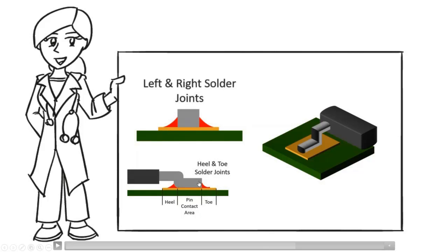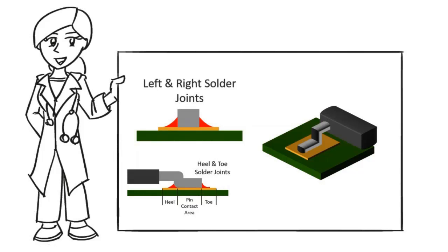So you can set up design rules that say, how much toe fillet do I want, how much heel, how much contact area there is, side fillets, in order to produce a good quality solder joint, plus being able to verify, did I put the pins all in the right place on the part? Is the pin shifted or not in any direction? You're basically modeling up the design to confirm that your solder joints are going to be acceptable in the assembly process. This is probably the number one thing that your contract manufacturer is also looking for when they do validation on your designs for you and they charge you for it.